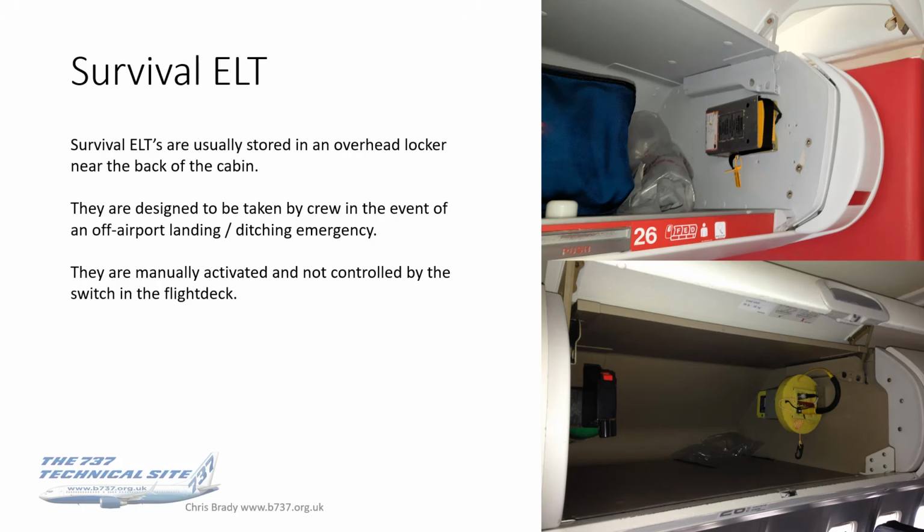Okay, this ELT is different. It's a survival ELT, is what it's known as. These are usually stored in the rearmost locker in the cabin, and that's because they're designed to be taken by crew or, well, passengers if they know what to do in the event of an off-airport landing or ditching emergency.